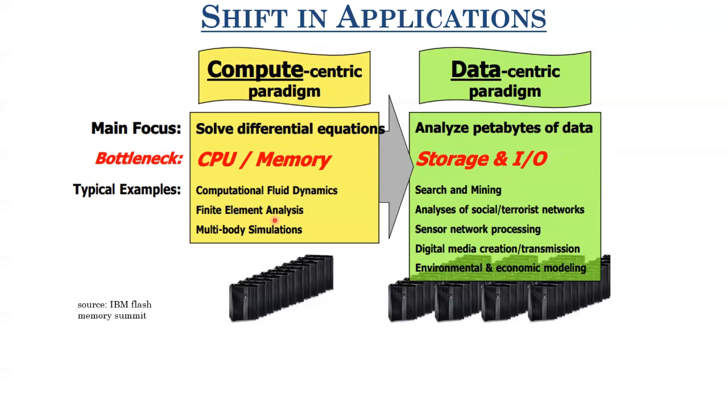So you can understand that there has been an order of magnitude increase in memory. But if you look at processor speed, it has remained more or less the same. That is because of this bottleneck, which is also called the memory wall. Every time you have to access any data from memory, it leads to a large amount of energy consumption, and it adds to the latency.